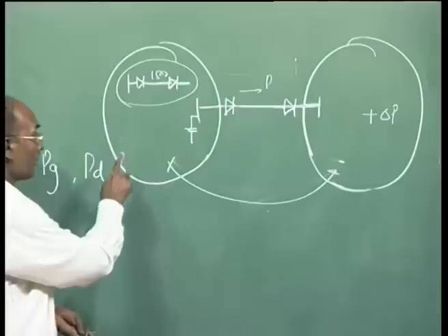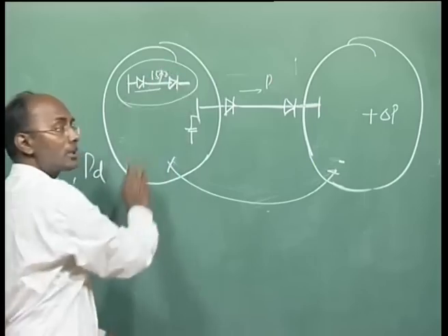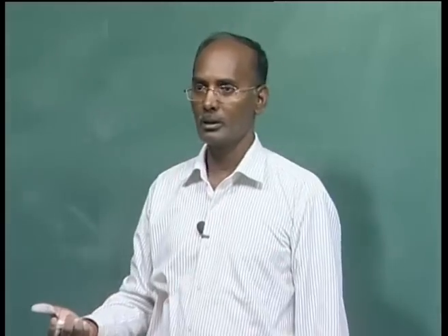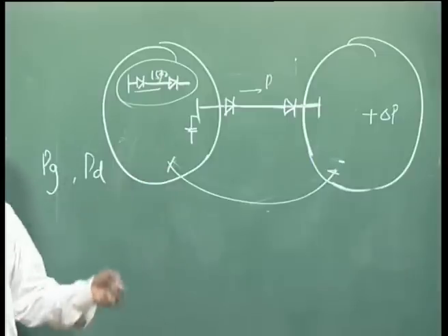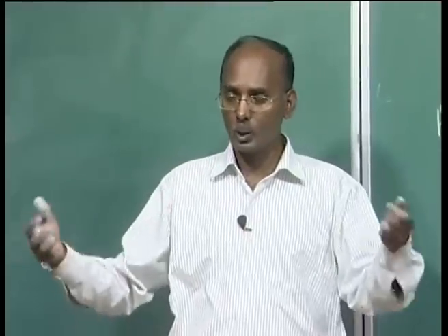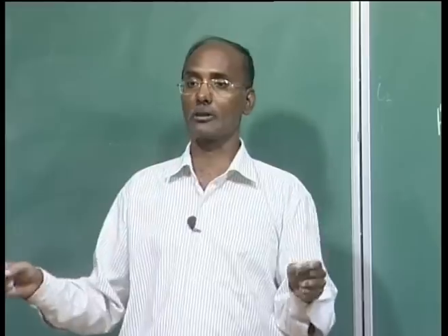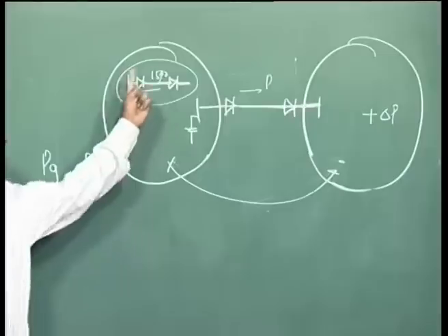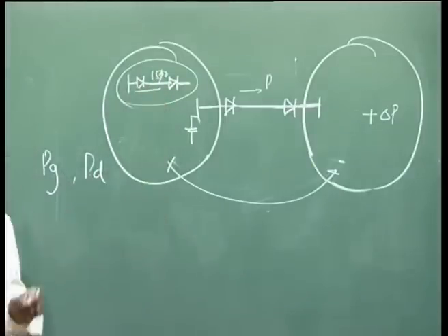So this will be flowing as it is. But if some lines are going to overload, momentarily we can increase this power for a few minutes, and then we can reduce our power levels, generation and load balance, in such a way that no line should be overloaded even with the outage of a few lines. So in the emergency we can operate it this way. Now at that time this 1500 setting is no more required.